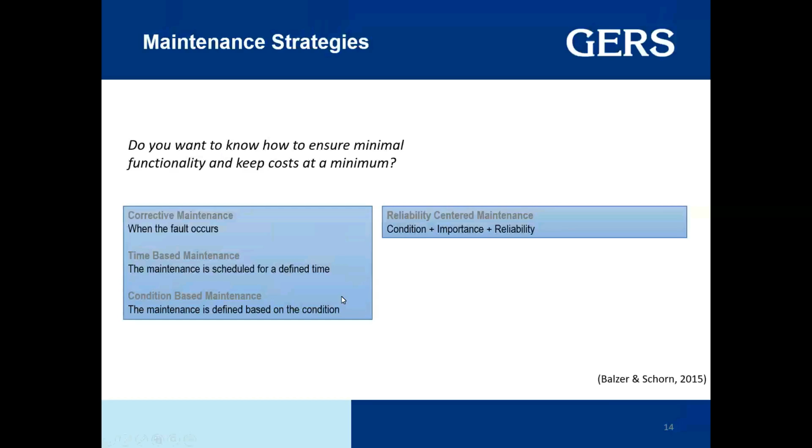Now we are adding here one that may be more complex. For example, the condition-based. And when we speak about the condition-based, we need to have a measurement about how is the condition of the asset. Which kind of testing do I need? How could I identify if my asset is in good conditions or not? And we are having here different experiences, where we need historical profiles, we need the experiences of the engineer that has been in contact with the asset. We need to attend the different references, because having a measurement on the condition is really a big state of the art.